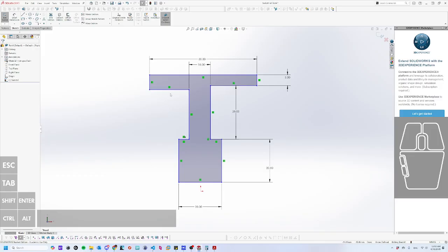And so what I can do is, since these are the two objects that I want to add a relationship between, I want them to be flat, I will control click, and you can see it highlighted, select both of them, and then that adds all the possible relationships that I can apply to the two of them. In this case, there's two options that would get me the result I want. If I make them horizontal, oh, never mind. Looks like horizontal just adds them individually to each line.